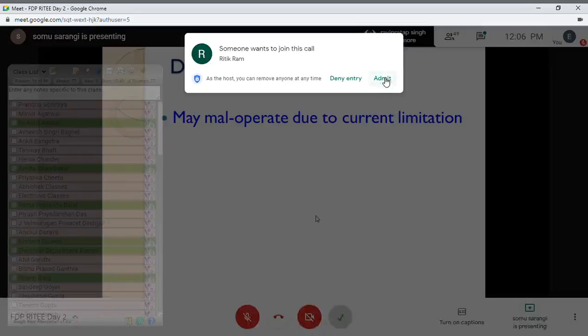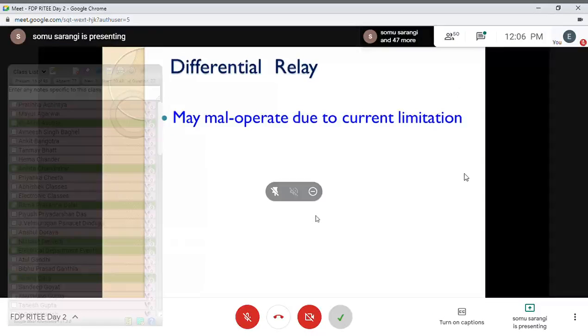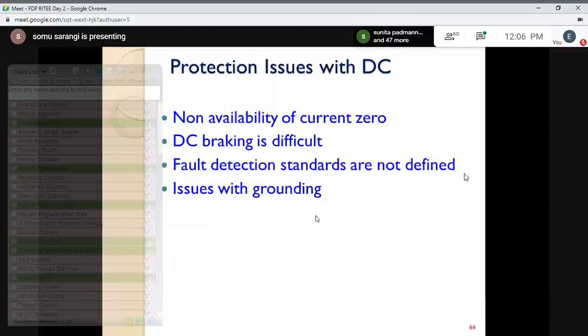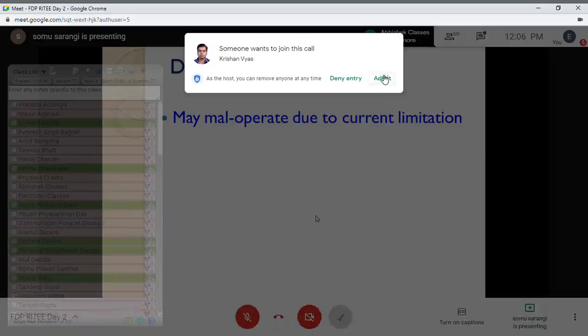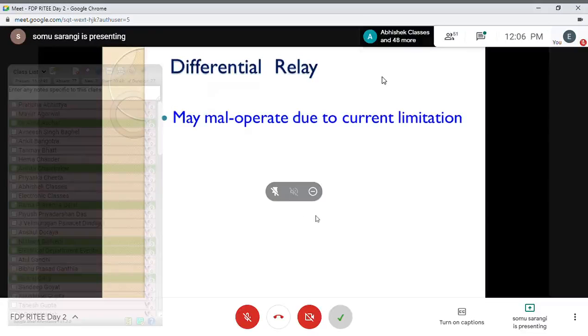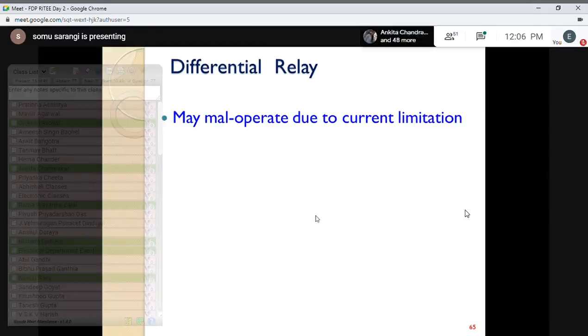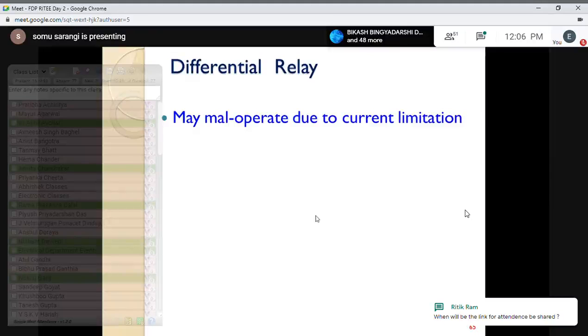Differential relay has another problem: when you consider the communication system, it will increase the cost of the protection system. The current limitation occurring in our system because of the different control techniques causes a problem, because the phasors we had from the synchronous generator were something different earlier, and now the control technique modulates the phasor in our system. So the phasor-based technique or phasor-based analysis for the fault that we have is not effective, or not applicable now.